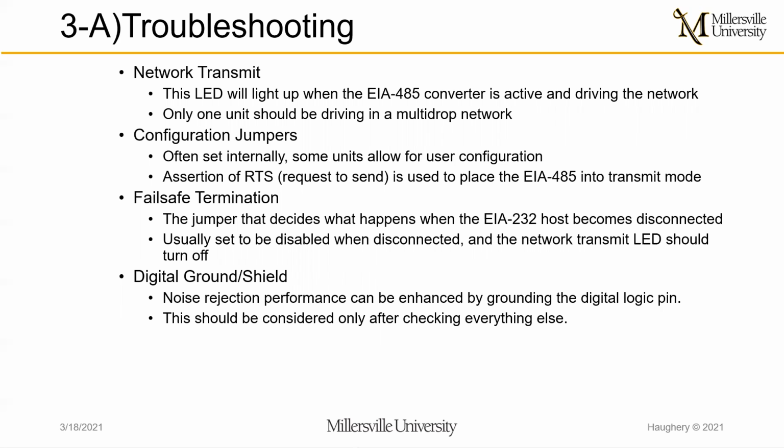The assertion of the request to send protocol is used to place the EIA-485 into transmit mode. The failsafe termination is a jumper that decides what happens when the EIA-232 host becomes disconnected. Usually, this is set to be disabled when disconnected, and the network transmit LED should turn off.